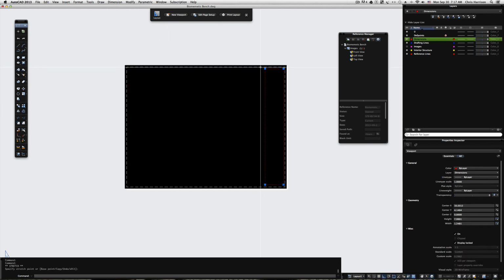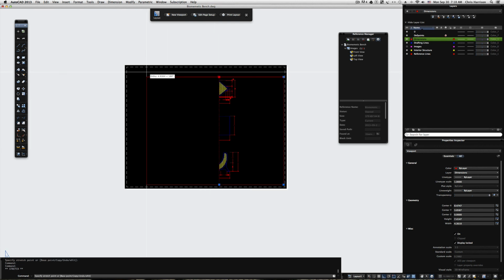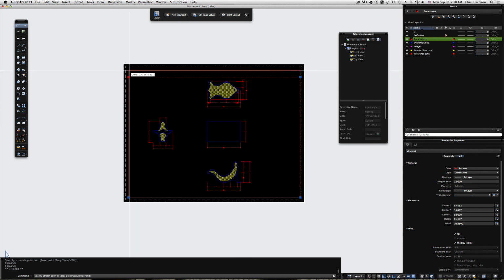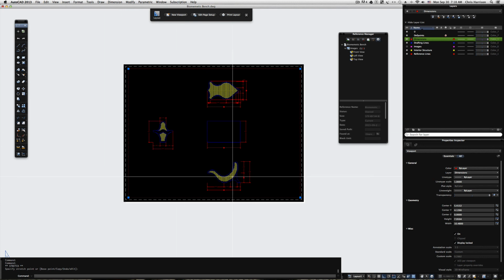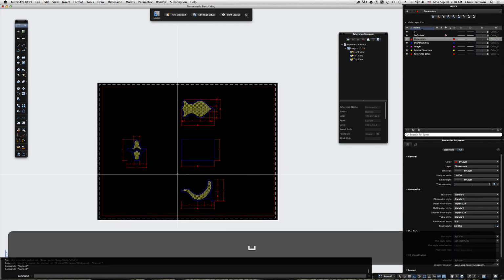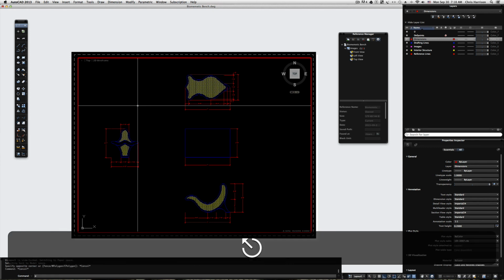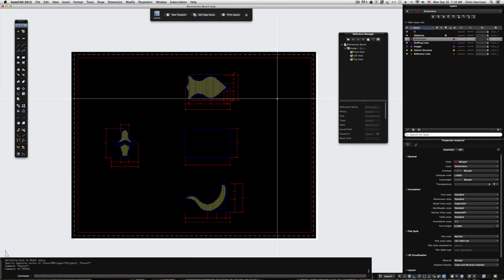so my page is already set up, but sometimes your window, and this is a viewport. Viewport is your window into the CAD world, into your model space. It's like a window. So you might have to move it around and adjust it, and I'm just grabbing the grips and dragging it out to make sure that it fills the frame of the layout that you've created. Now you can scale within this, but we're not really worried about that because this is dimensioned. And I locked this one. I did lock it. Let me unlock it.